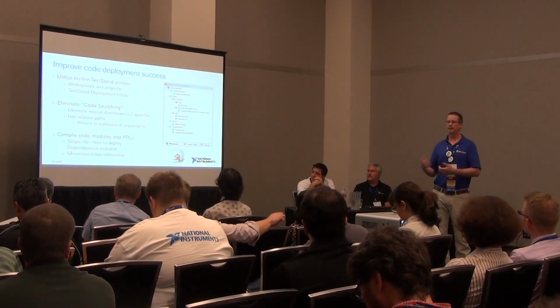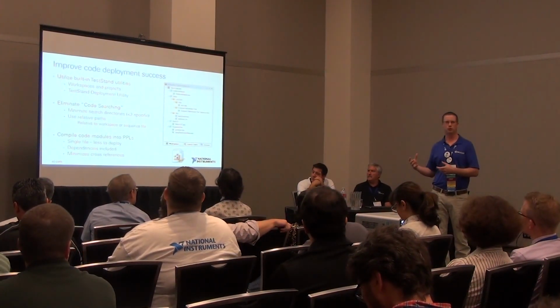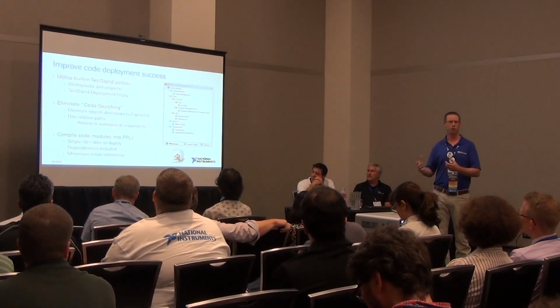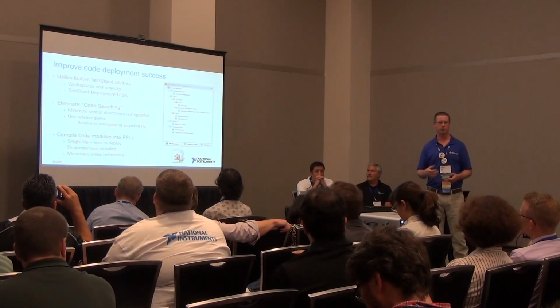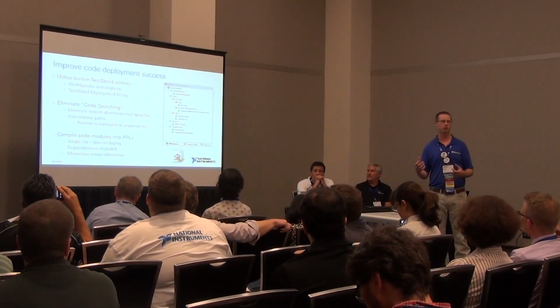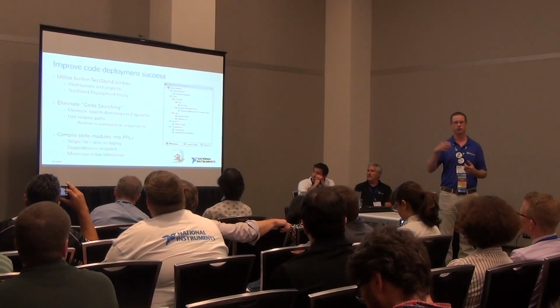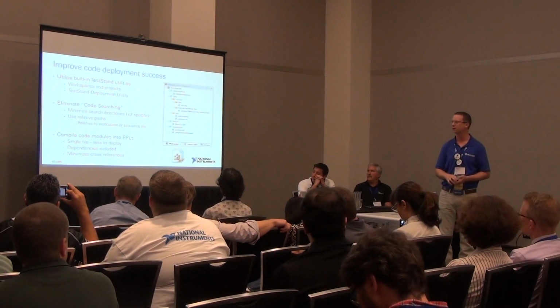And with TestStand you have these workspaces and projects available to help you organize your system. And by using those you get the TestStand deployment utility, which is essentially a build script that allows you to create an installer that you can use to install on each of your deployment systems.